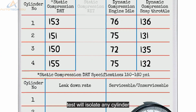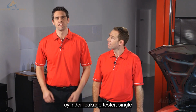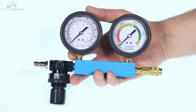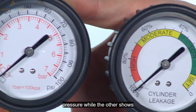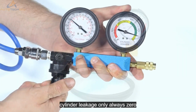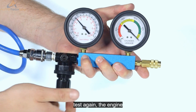Performing a leak down test will isolate any cylinder pressure loss found during a compression test. There are two types of cylinder leakage tester, single gauge and dual gauge. We'll be using a dual gauge type for this test. One gauge displays regulated pressure, while the other shows cylinder leakage. A single gauge tester displays cylinder leakage only. Always zero your gauge before conducting a test.